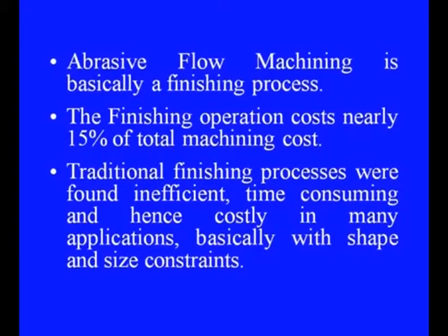This abrasive flow machining process is basically a finishing process. As we know, this finishing operation is very important as far as manufacturing is concerned. Almost 15% of the total machining cost is for finishing a part only. However, these traditional finishing processes were found inefficient, as I told just now, and time consuming, and hence they are costly as well.